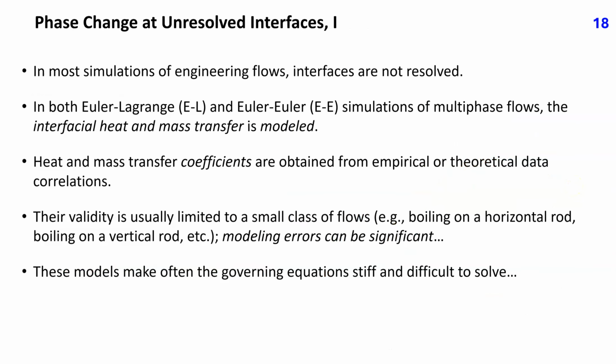In most simulations of engineering flows, liquid-vapor interfaces are not resolved. Therefore, in both Euler-Lagrange and Euler-Euler types of simulations of multiphase flows, the interfacial heat and mass transfer is modeled. Heat and mass transfer coefficients are obtained from empirical or theoretical data correlations.